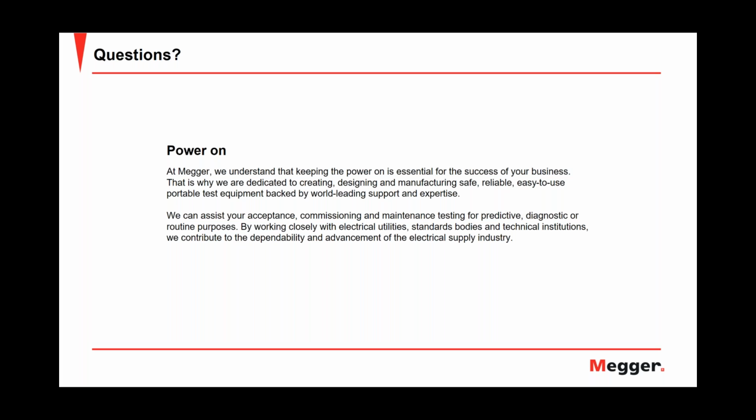You ionize this air gap, you apply voltage, and at one point the air cannot hold the voltage anymore, and it will just spark. For a very, very short time, an arc will be established. Current is flowing from the surge generator through the fault and back to the surge generator on the shield of the cable, and then the energy is dissipated, and the arc is gone. And because the air gets displaced out of the pinhole, that is the bang sound that you create there.